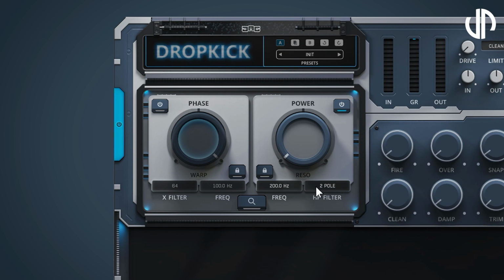Additionally, you can choose the slope of the high-pass filter, indicating how much of the subharmonics below the fundamental are removed. The 2-pole option has a slope of 12 decibels per octave, and the 4-pole option has a steeper slope of 24 decibels per octave. There are 2 variations for each high-pass slope. The standard version is clean and precise, while the other version introduces a boost around the cutoff to enhance the bass. We've also included an option to turn the high-pass filter off if you want to utilize the resonant peak to boost a higher harmonic or for other creative purposes.